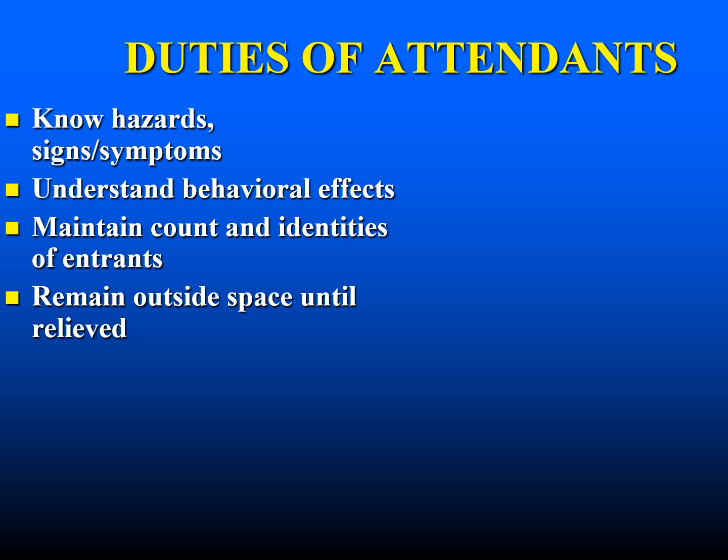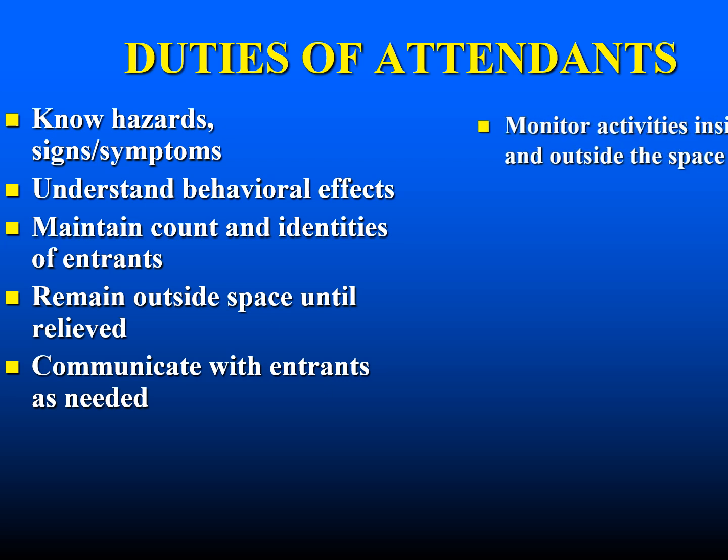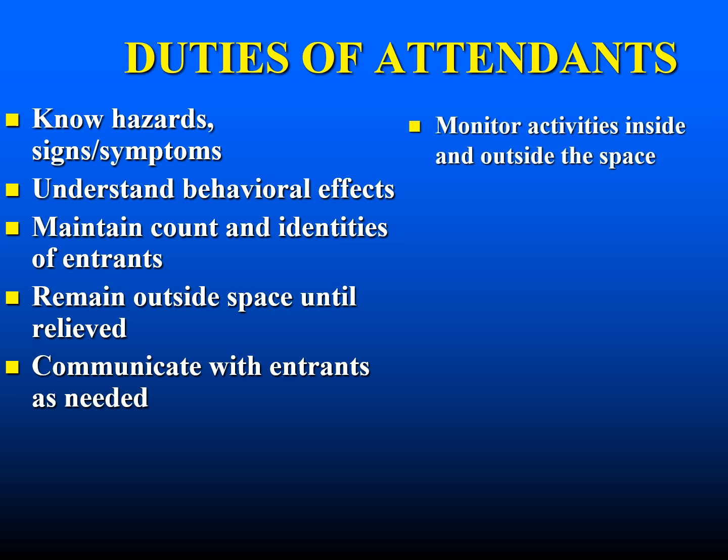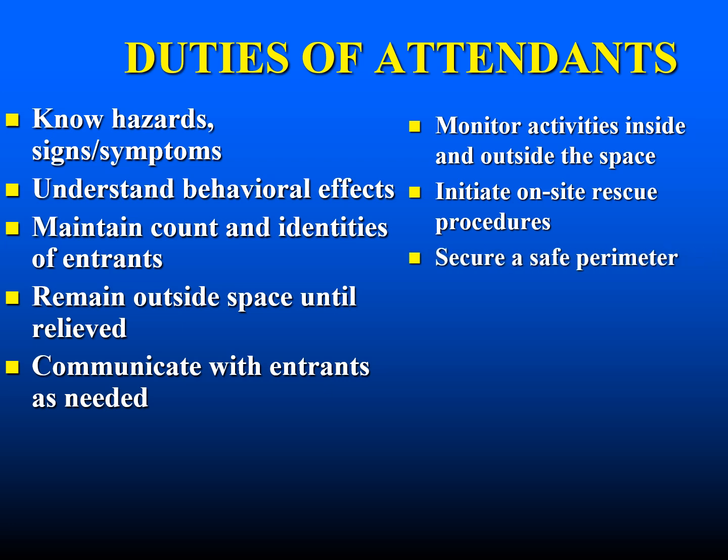They must remain outside the space until they are relieved, and they must communicate with entrants as needed. They must perform monitor activities inside and outside the space, and initiate on-site rescue procedures, and secure a safe perimeter. These are all duties of attendants.